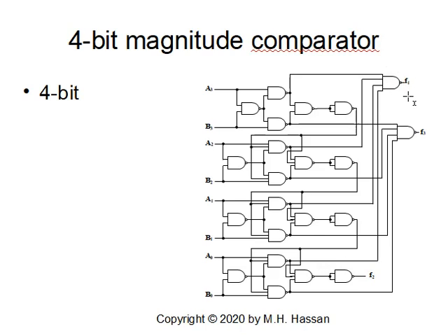And for F3, which is A less than B, we get the outputs from this NAND gate, this NAND gate, this one and this one, and this definitely will give me F3 in this 4-input NAND gate.